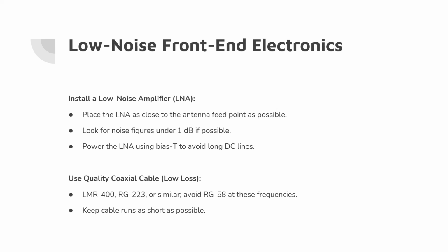Well, with our experience, our radio shed where the main computer is about 30 meters from the dish, and Lord knows what coax cable we were using, but we lost about 10 dB from the amplifiers and SDR amplifiers in the dish down to the detection in the shed using coax cable. And so that was what prompted us to move everything to the dish.